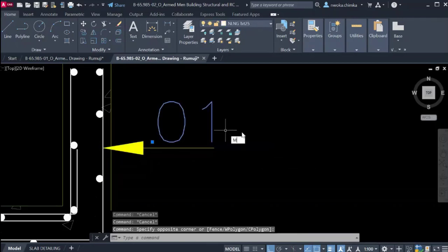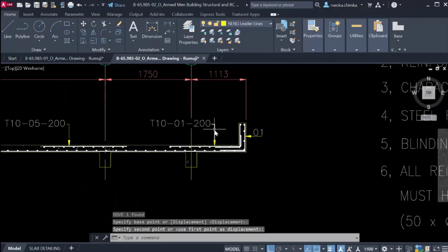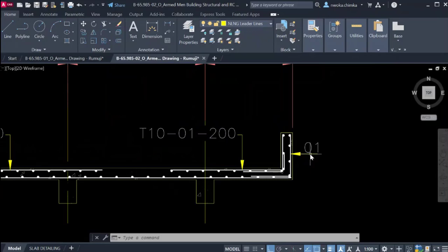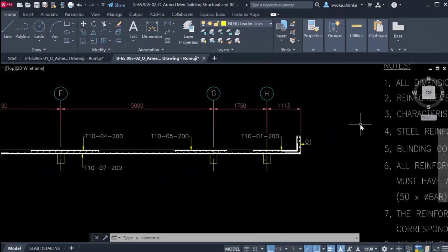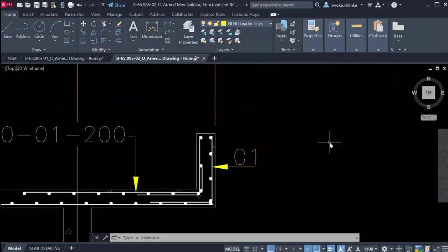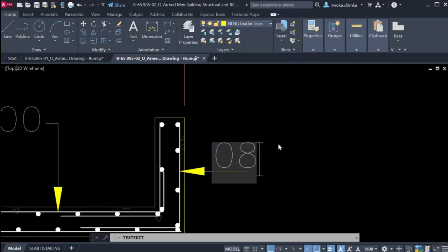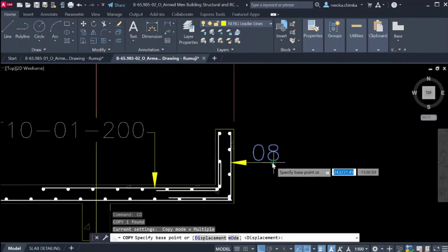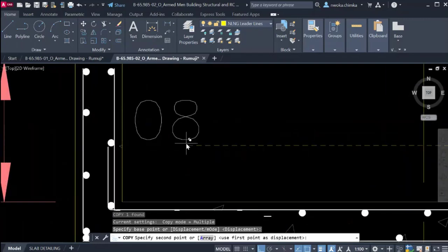So you can see this is also another way, if you don't have a space in this place, you just use the bar mark to note it. Again, the next thing I'll do is this bar mark stops at 7, so this will be bar mark 8. Automatically, this also becomes bar mark 8 because they are the same length. This one here also becomes bar mark 8.